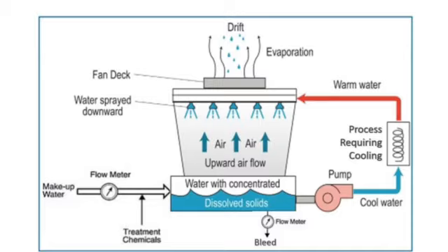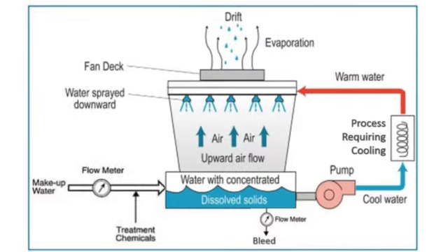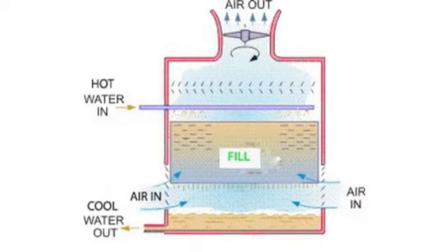The water is exposed to air as it flows throughout the cooling tower. The air is being pulled by a motor-driven electric cooling tower fan. When air and water come together, a small volume of water evaporates, creating an action of cooling. The colder water gets pumped back to the process that absorbs heat and the condenser.